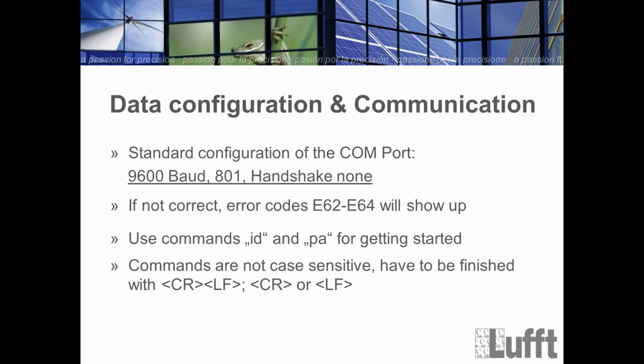If you connect it for the RS-232 or the 422, you need a kind of terminal program, and the terminal program should use these COM port settings. It's a little bit different from the UMB COM port settings, which always run at 19200.